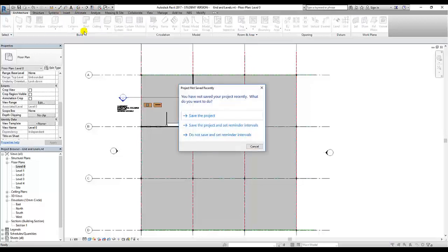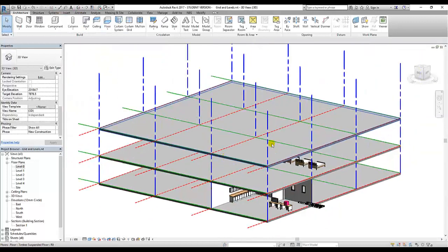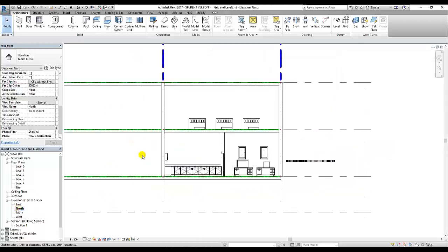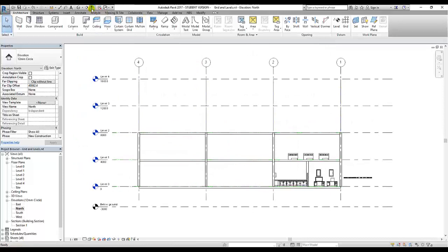So if I go into 3D, let's cancel that. I've created this grid because you can't see these things in the 3D view. So I've got these grid lines. So the Z-axis, which is the one going up, this is an elevation, is in blue. The red is the X-axis, and the green is the Y-axis. Okay, and I've turned on thick lines, so we can see exactly what's going on.